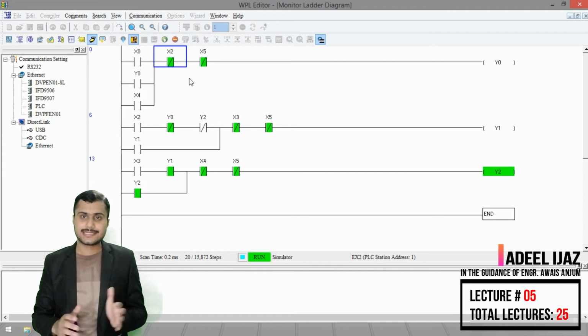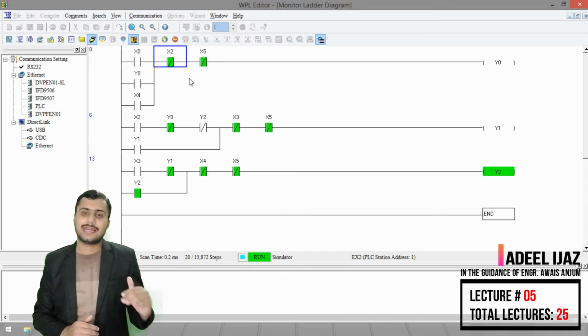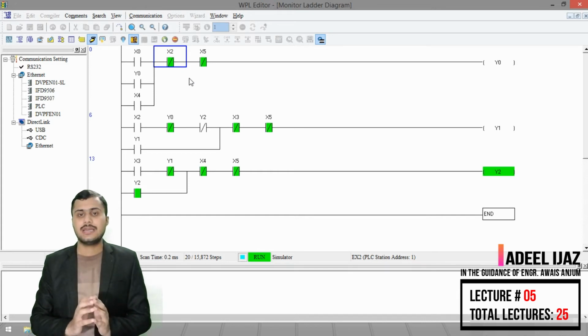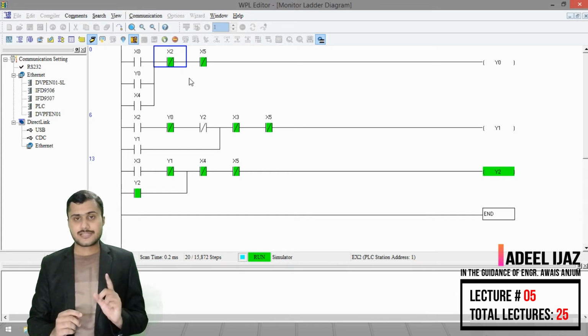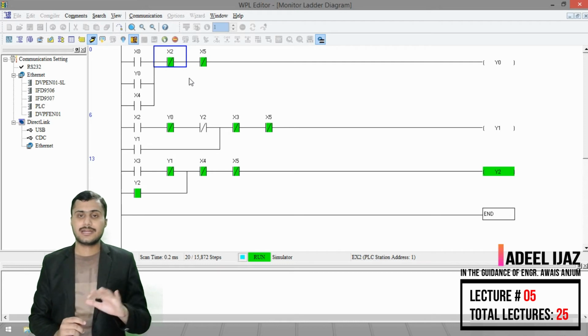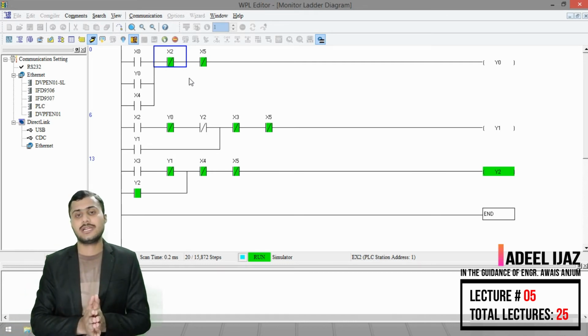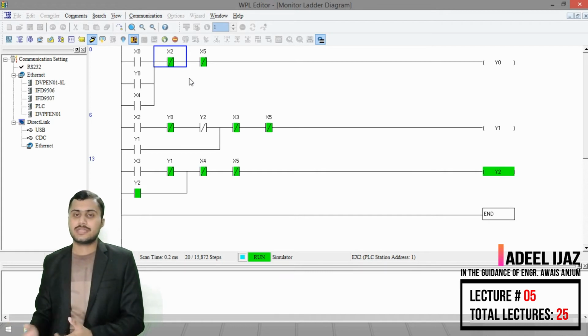The tank gets empty. So when the liquid hits our last sensor, which is sensor number 3, then our X4 gets activated, and it will stop the outlet pipe. I mean, it will stop the liquid from exiting the tank.